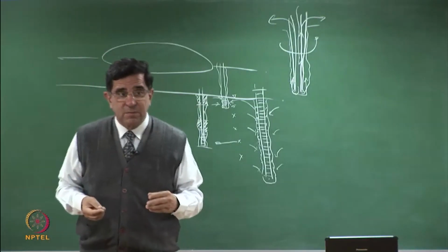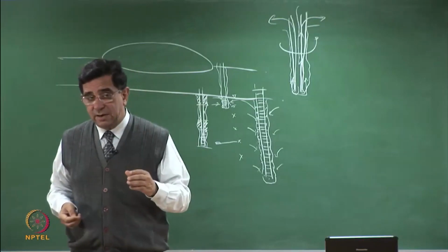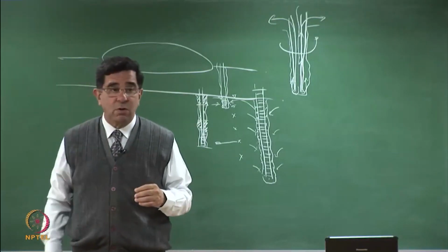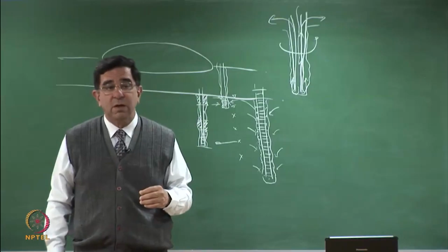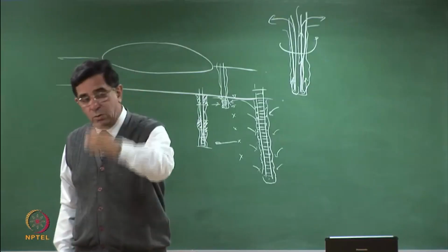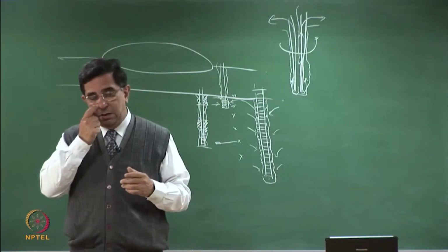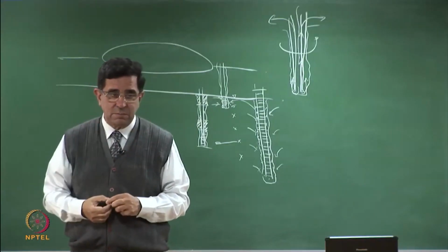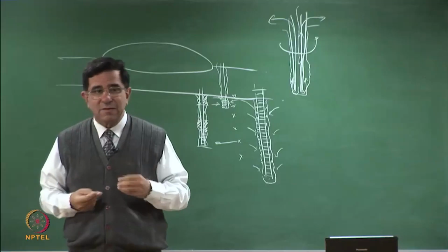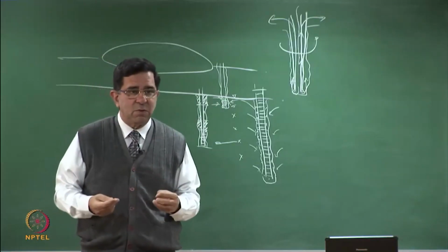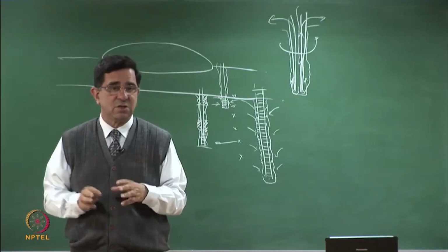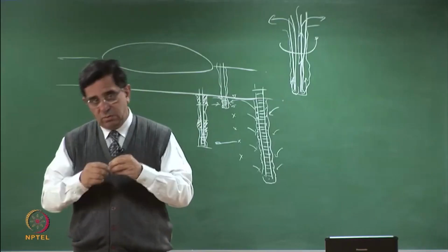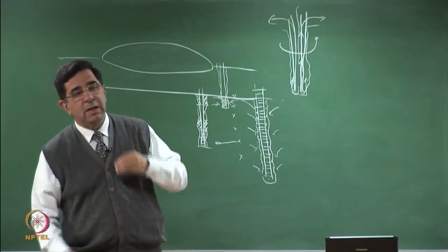Now, that is not what we do on normal wells and normal tube wells, and nobody seems to understand that. You will go to any landfill site and ask, do you have a borehole for monitoring groundwater? Yes, sir. There will be one borehole. Where is the water table? 15 meters deep. How deep is this? Sir, this is 25 meters deep. But what are they sampling? Are they sampling from 15 meters, or 25 meters, or 20 meters? It's all mixed. You can have even a deeper well.